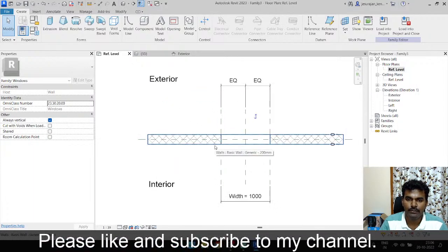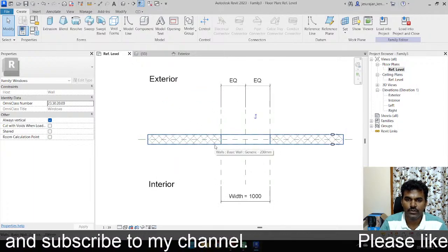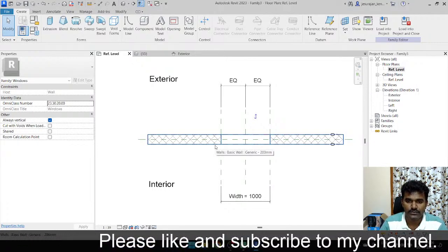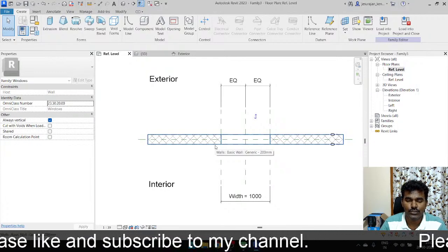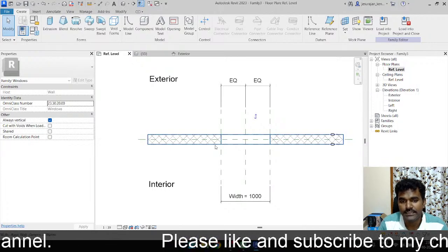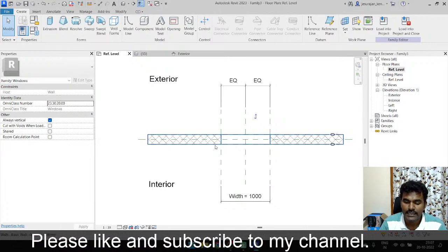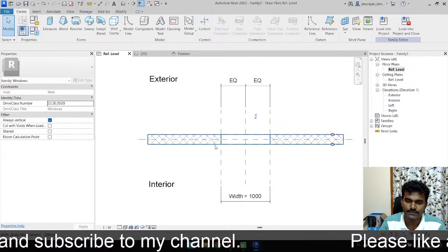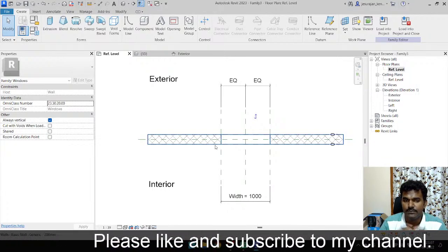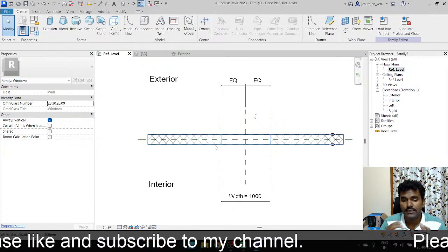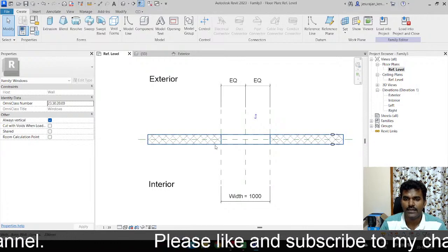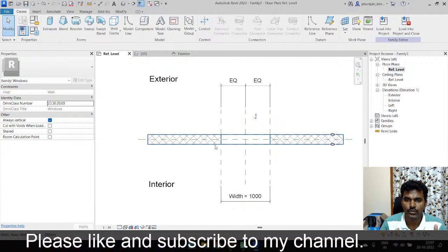Okay, so we are going to make our window frame. Now the very important thing you need to fix initially, even before creating the geometry, is your style of creating a window. Will you take an interior side or exterior side? That's a very big decision when you are creating a window family, because when you are in the project you cannot just move the window horizontally, you can only flip the window front and back.